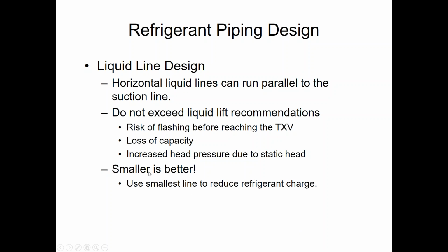Undersizing liquid lines, although I say right here smallest line is better, undersize can reduce capacity on you too. So be careful with undersizing. And it's simple to do. Just stay by what the chart tells you to use. Go on the chart, here's your liquid line size, here's your suction line size, or your discharge line size. Do what the book says. It's all been tested and rated, and we know it's accurate.